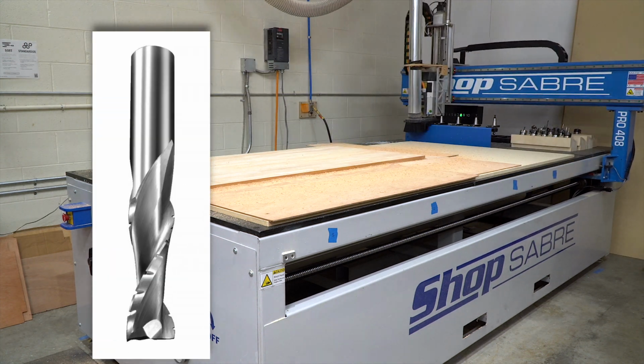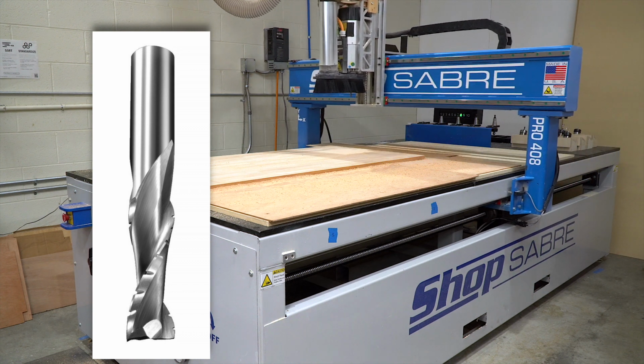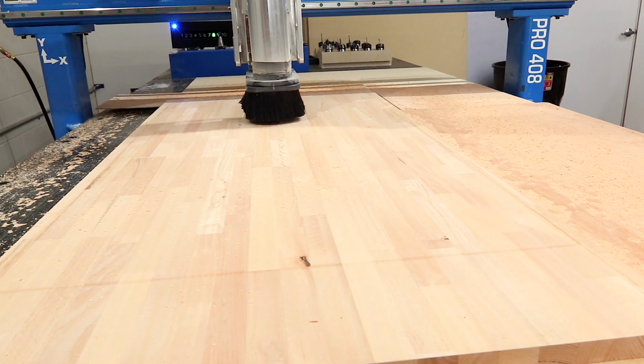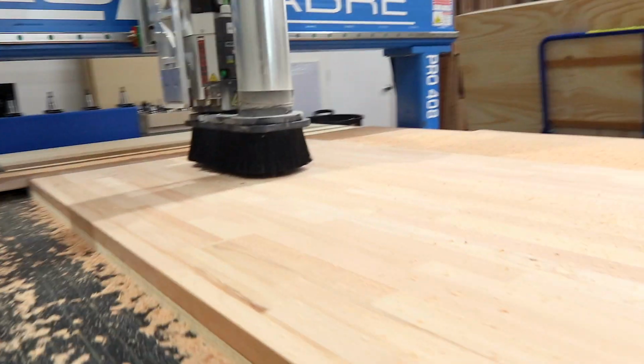This is the Vortex 1440. It's the semi-roughing tool. It's an upcut 2-flute, 1/2-inch diameter with chip breakers, so that just breaks up the chips a little bit better and is really great for roughing or slotting in hardwoods like this, because you're generating quite a bit of heat in any slotting operation.